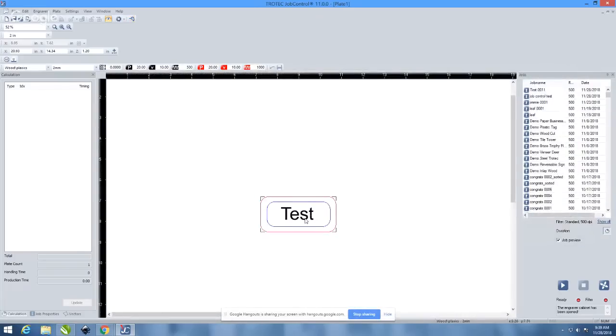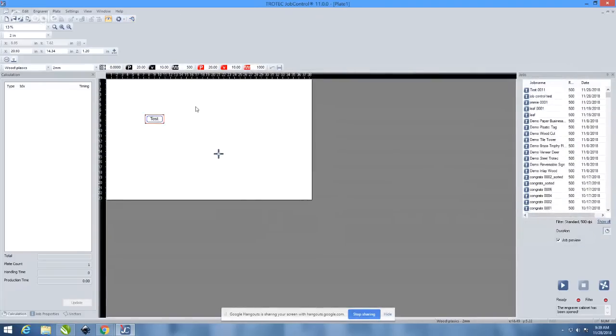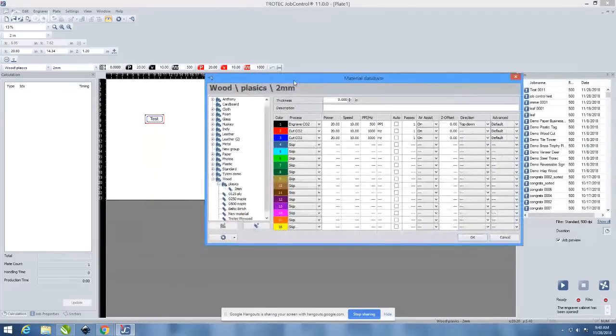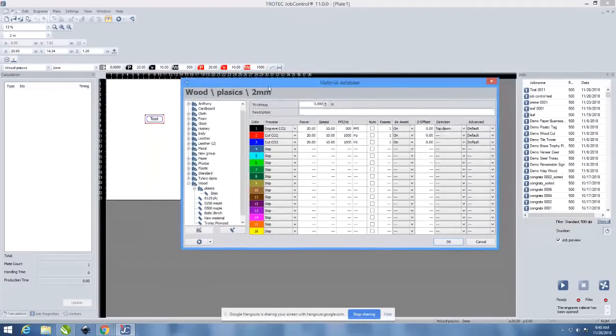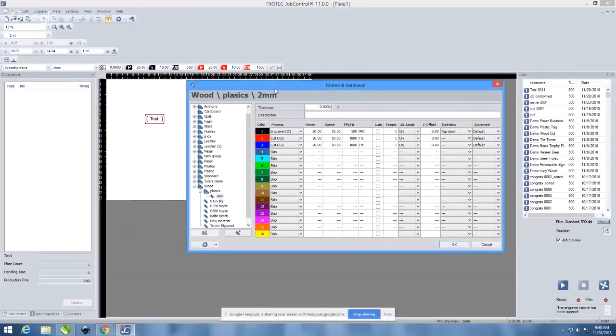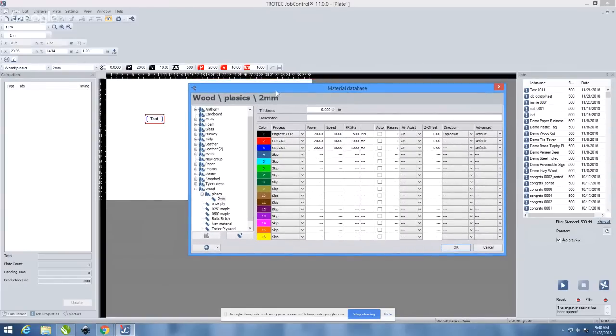And now we can see our blue line here. I should also quickly mention a lot of issues I had when I first started using the laser. When I did the cuts, I kept forgetting to set the line to the thinnest line. So in Corel, it's a hairline, and in Illustrator, it's 0.01, I believe. Is it 0.01 or 0.1, Anthony? I can't remember. 0.01. When in doubt, just go smaller.